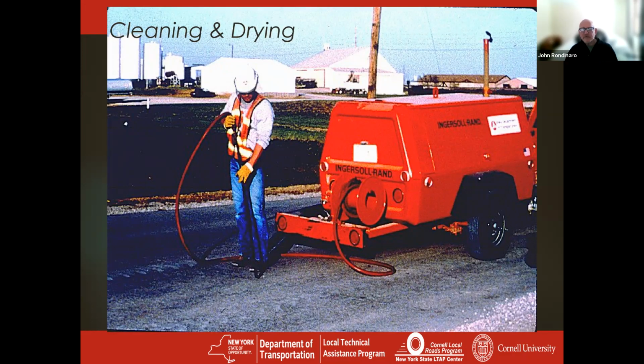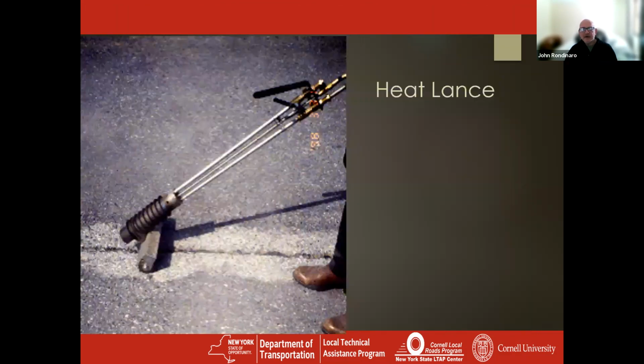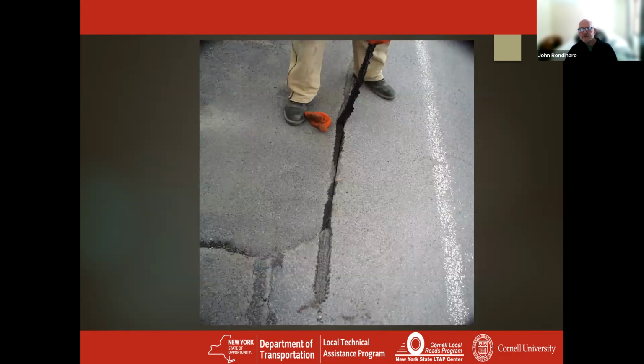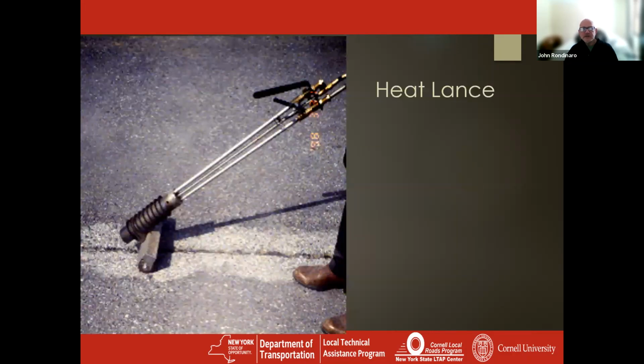And the one thing you want to remember when you're working with a compressor is you have an oil water separator installed, because you don't want to be blowing moisture or oil droplets into the crack. Otherwise, it's going to end up like this. No matter what material you use, if it's not clean and dry, that material is going to pull right back out. You can also clean and dry using a heat lance.